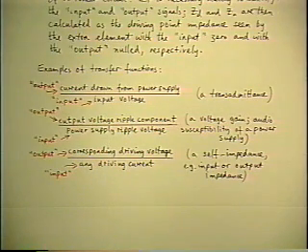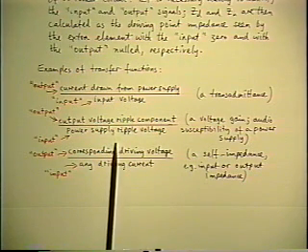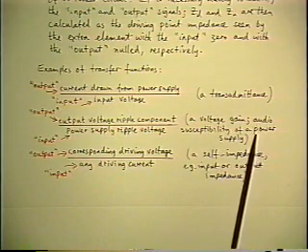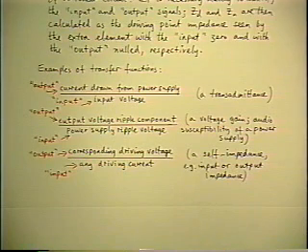Exactly the same sort of transfer function also applies to a regulated power supply itself. That's actually an amplifier as well. It takes an unregulated rectified line, maybe with a lot of ripple on it, and there is also a specification on the power supply that says its regulated output voltage has to have less than so much ripple in it. So that's another voltage transfer function, which is often called audio susceptibility. That's an important specification of a power supply.